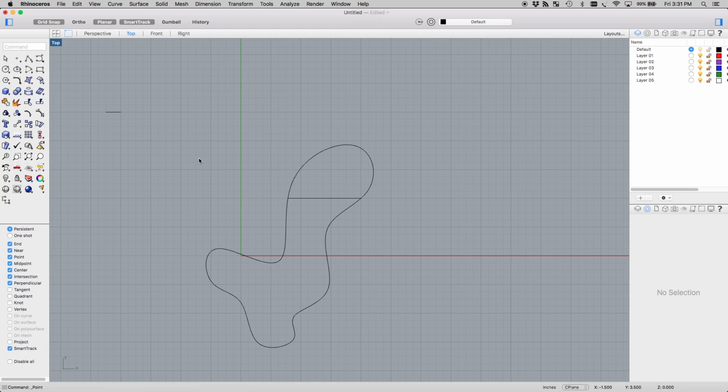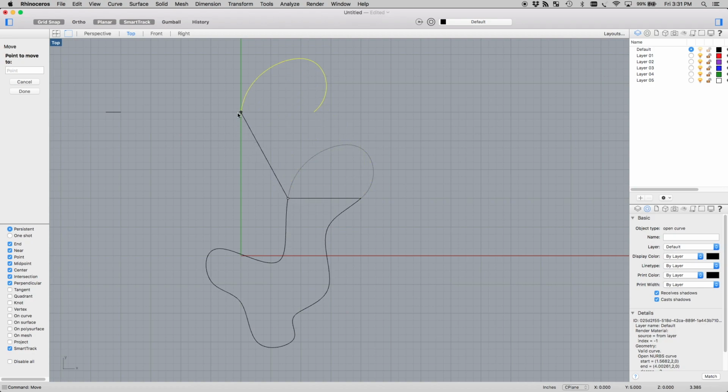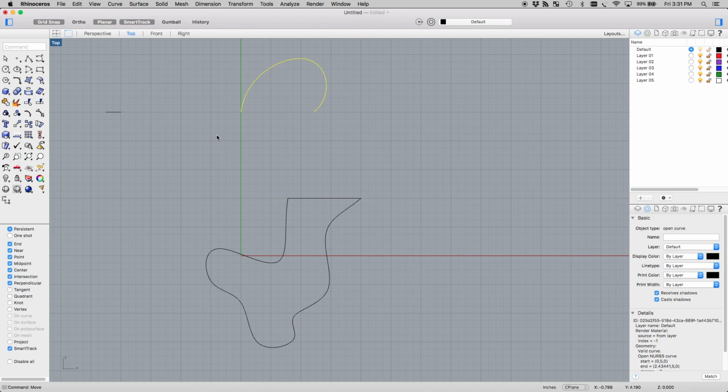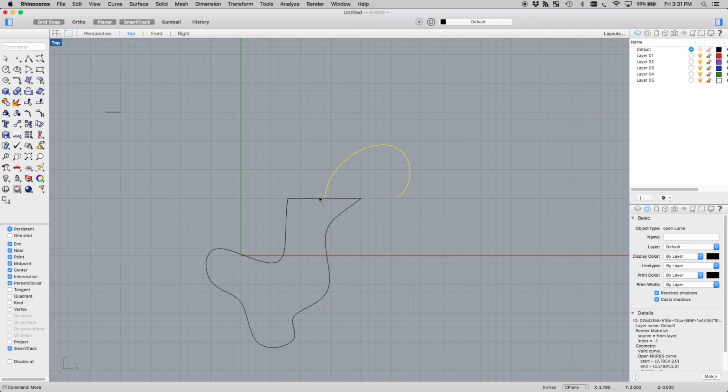The move command allows you to shift the location of objects by selecting a starting point and an ending point. Here, let's move this back using an object snap to the middle of our line. Note, your 2 reference points do not have to be on the objects.